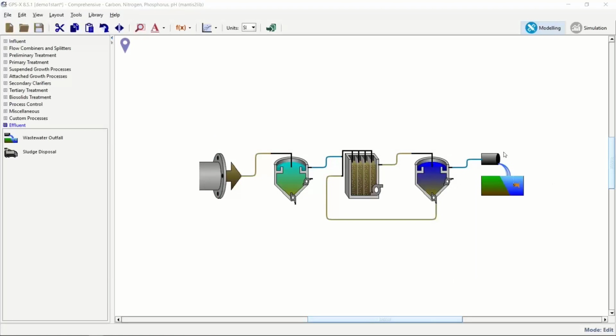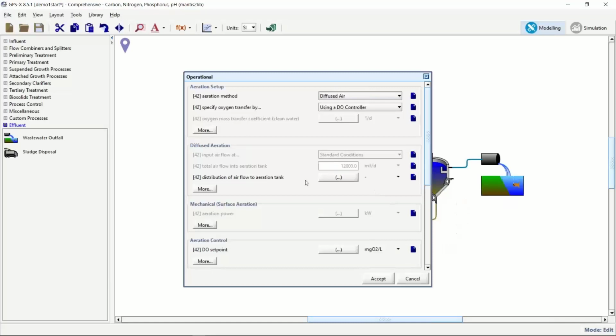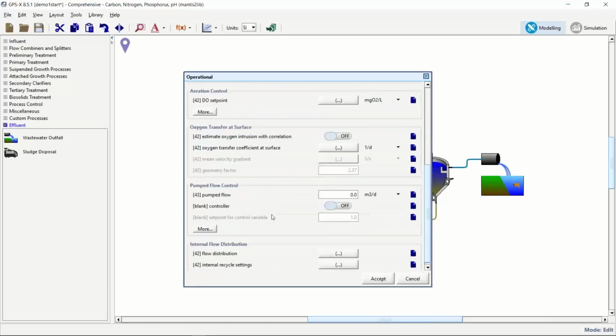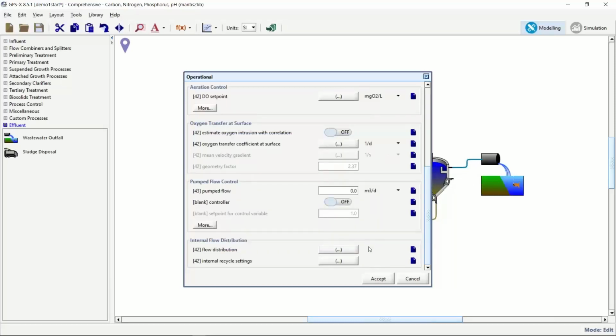So what we need to do is now we'll go back to the influent part and slide down to the bottom. And now we'll see that we only have 3 reactors and 100% of it is going in the front end here. Okay, same thing for the RAS. When we look at that connection point that's on the lower side of the left coming in, that's also 100% of it goes in the front. Okay, so no changes to be made here, but we did check, and this is where you would make the change if that was part of your BNR design.